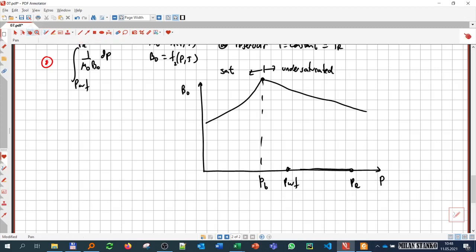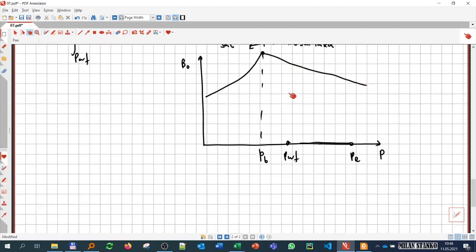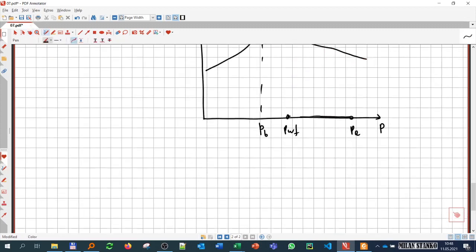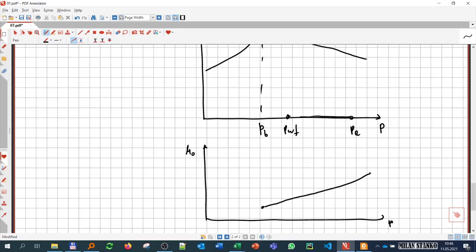The main message is that as pressure goes down, BO goes up, so it has an inversely proportional relationship with pressure. The oil viscosity actually does the opposite. It's increasing, because everything is getting packed up, with more mass in the same location, and that's why the viscosity is increasing slightly.